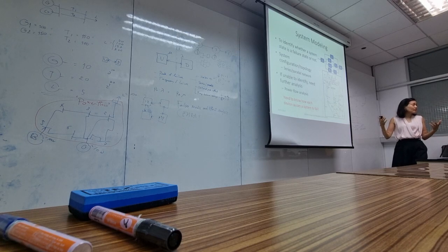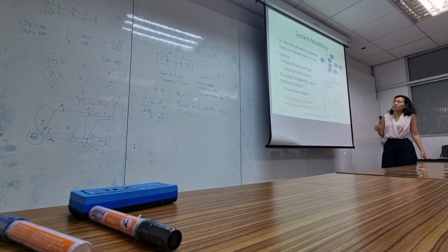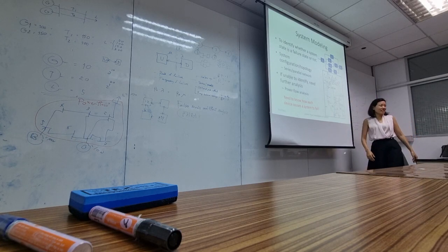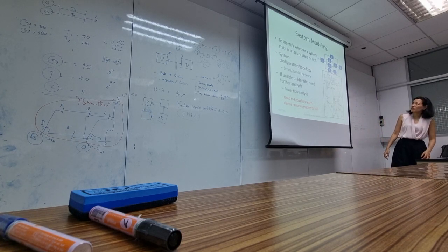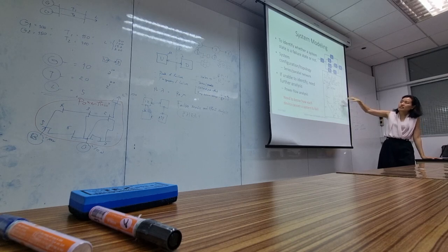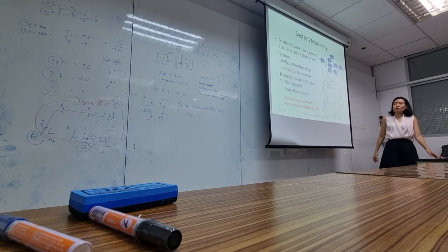As for the system, you need to know how it interconnects. If it's just series and parallel, it is very easy to calculate. But power systems have all the interconnections, a very messy network. This is an IEEE bus system, I think. This system topology we cannot classify as simply series or parallel, so we need further analysis, which is why we need the power flow.